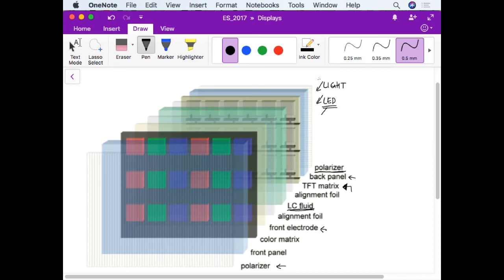I mentioned before that the AMOLED is more efficient from the point of view of energy, and you can probably see the reason. With the AMOLED, in order to have a black, you have all the pixels off. All the LEDs are off. With the LCD screen, when you have a black, actually you have the backlight that is white, and you have all the LCD off so that you don't see the light. But you are basically consuming power. That is the main difference. The power consumption is constant for the LCD screen, but it can vary depending on the color for the AMOLED.